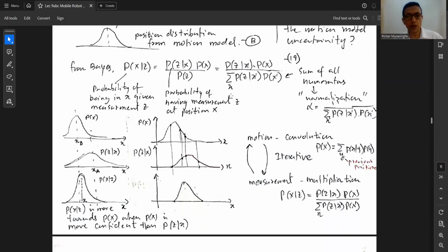All right. Now, what we are trying to do here is to bring two probability density functions, both normal distributions, and multiply them together. On one hand, the vehicle model; on the other hand, the sensor model. When you combine these two, you get another distribution function, which is also normally distributed. So in one go, you can generate your location and standard deviation or variance without having that problem earlier. If you were to use the histogram distribution, the computational complexity increases, but now it's not the case.